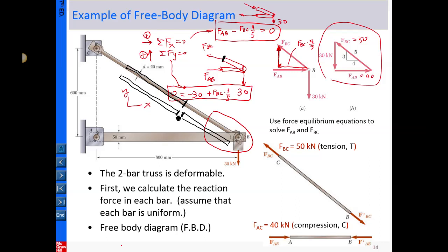And this is the same cross section, and the force on this cross section is pointing in that direction. So on this cross section, the force is action-reaction, pointing in that direction. So that is showing here, okay? So the whole bar is in static equilibrium. So this one must be equal to that one.